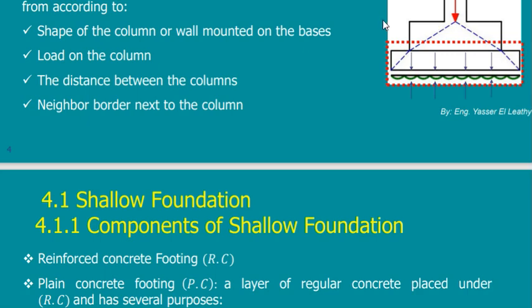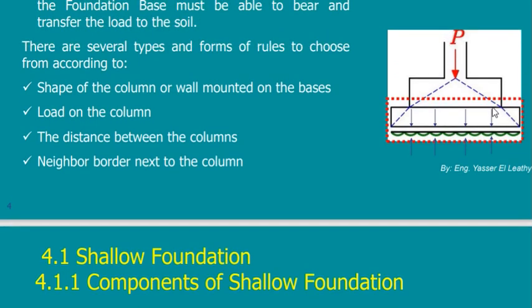But if you put something this thick compared to the RC, then I can use it, and I do some stress distribution. Let's follow what I mean. Here is the force P. This force will be divided into an area represented by this distance. So the load will be divided on this distance. It will give me a stress.